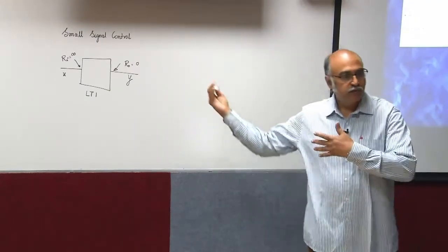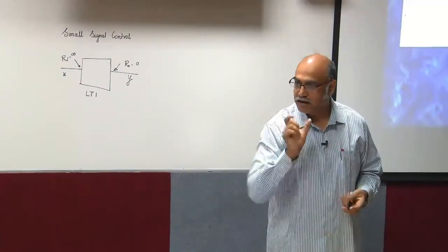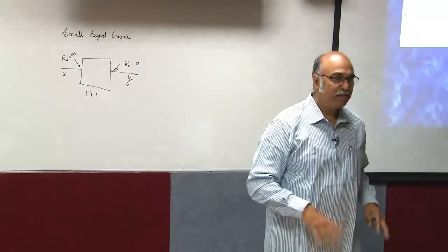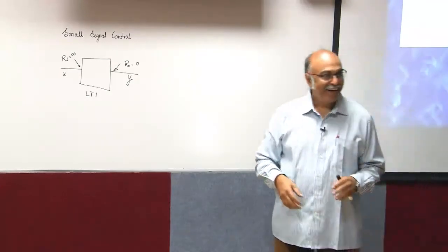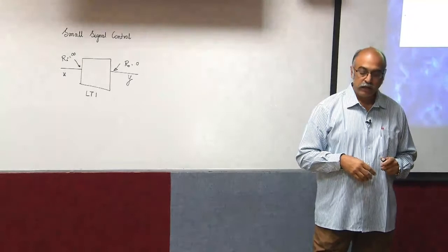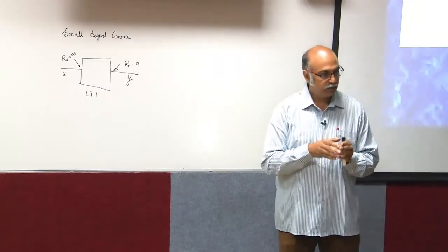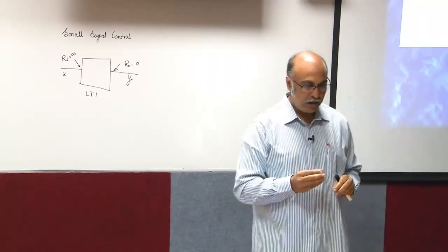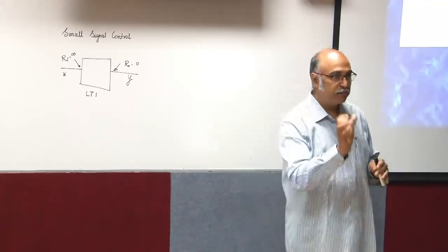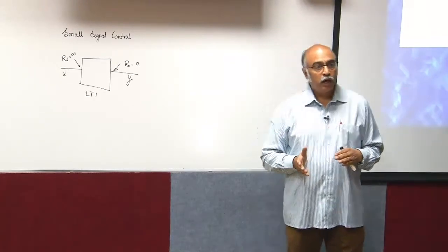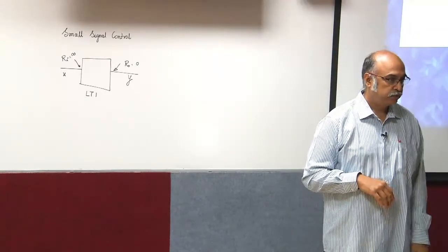So, most of the time what we do, we go like this, we do block diagram algebra and all those things, then we arrive at some number and we plug in the number, it will not work. Then you start trial and error. You could as well have started trial and error right from the beginning and tried to design the controller. So, we want to go as far as possible towards a much more formal way of designing the controller. When you design the controller, it should work. If not the first iteration, the second iteration, third iteration, it should improve and work. And it should as far as possible represent the physical system that you are intending to control. That is very, very important.